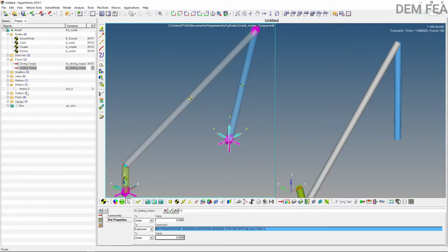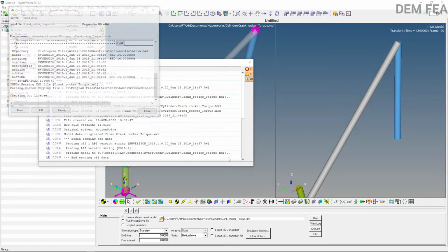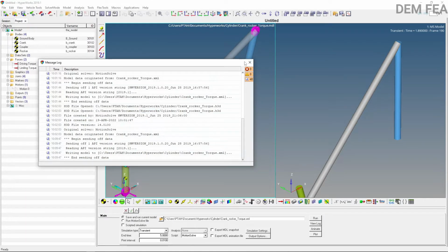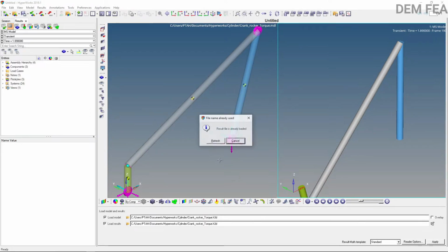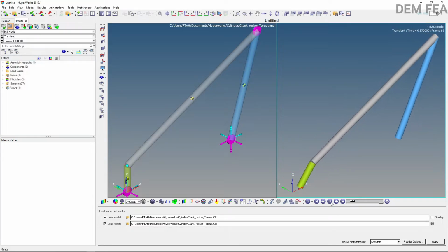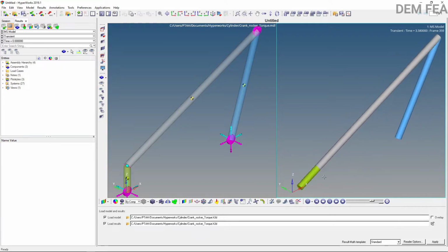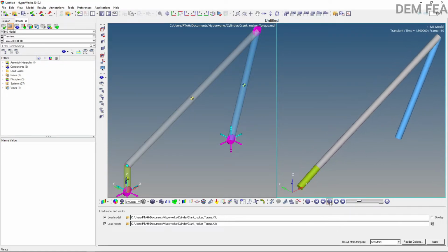Now we can come here. Now we run our simulation again, then we see what happens. We've added a limiting torque, so you can come here and animate, refresh. You see now it has limited, it's not rotating all the way. So that's how it's behaving.